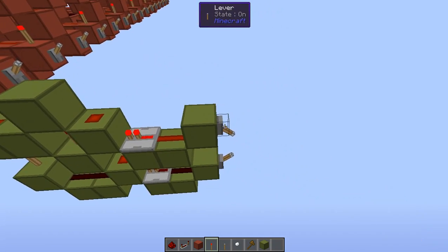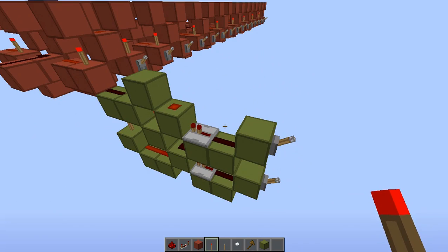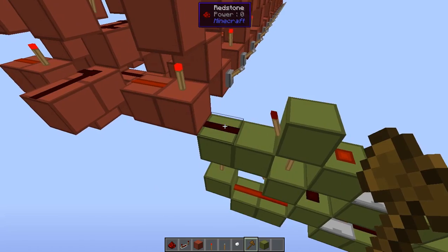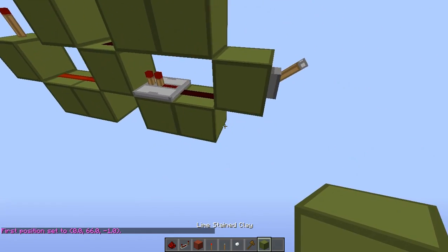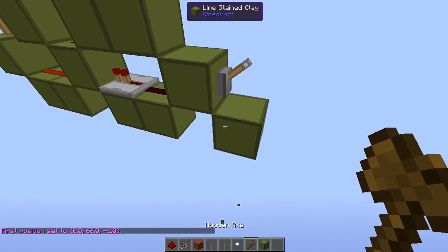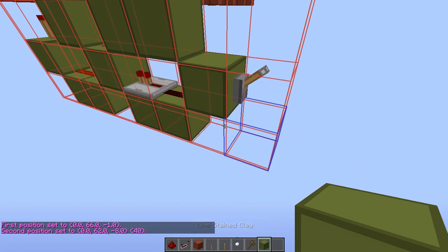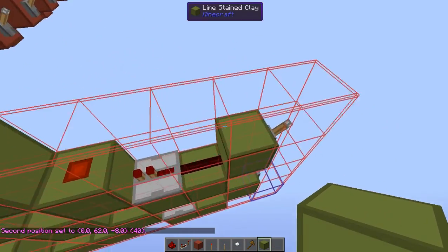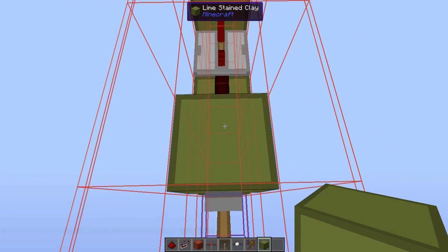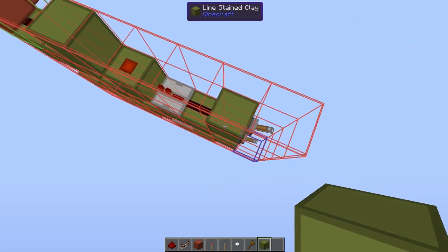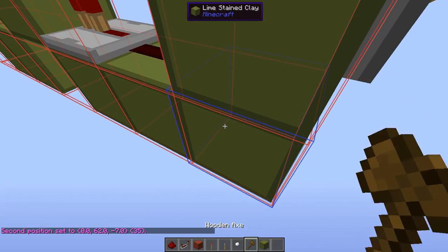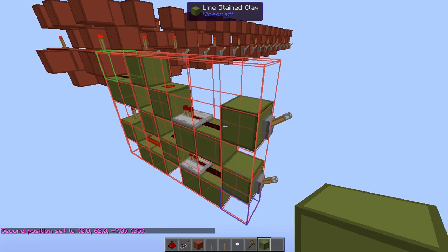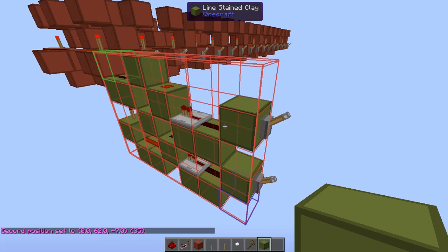And you may be wondering, why are we using an XOR? Because you told us that it's a NOT gate that we're using. We're doing not A, not B. Sorry, not A plus B. And that's obviously not what I've just built. So, what am I doing? The answer is that I am actually using an XOR because we want this to be not only an addition circuit but a subtraction circuit at the same time.